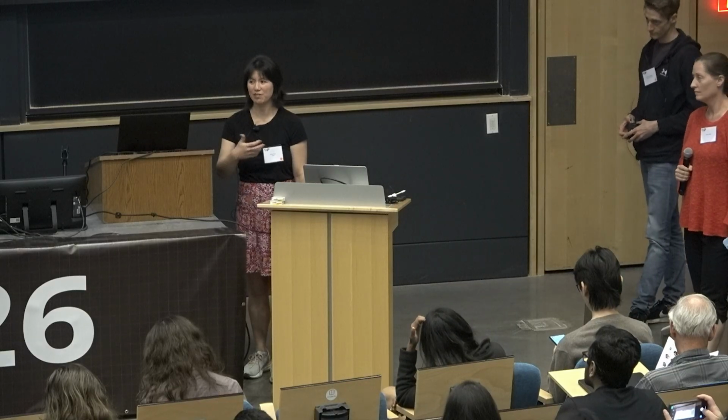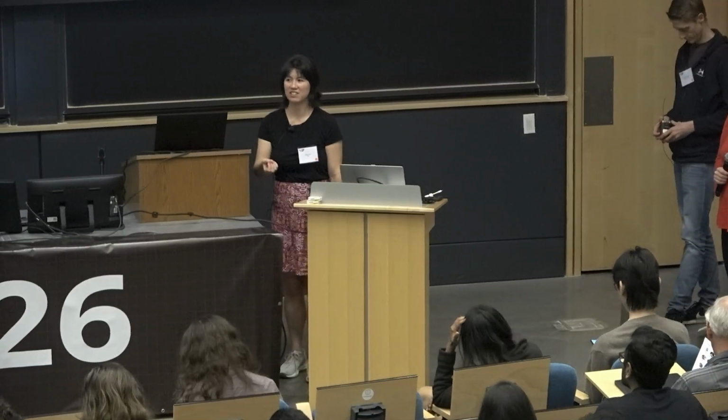Yeah, so the temporal multiplexing is just to do the color for the multi-source system. To show the color images, it's basically 3 frames. And then the second part of the question is, can you use fully incoherent sources or not use lasers at all? The challenge there is you get a trade-off between resolution and speckle, because it is the coherence of the system, the diffraction off of the SLM and the self-interference, that creates the image content in the first place.